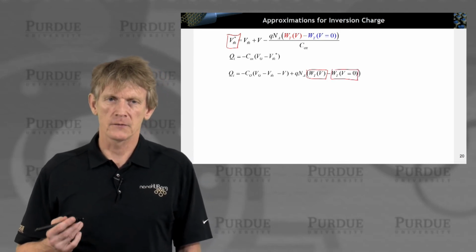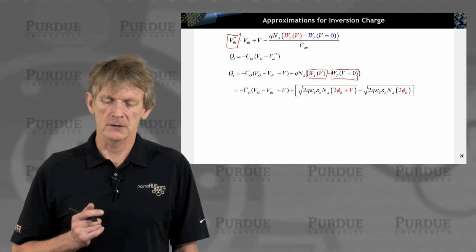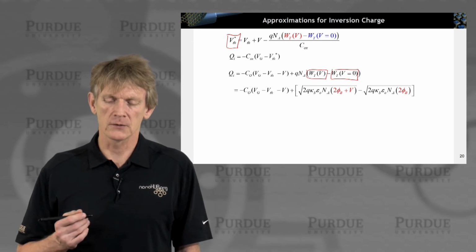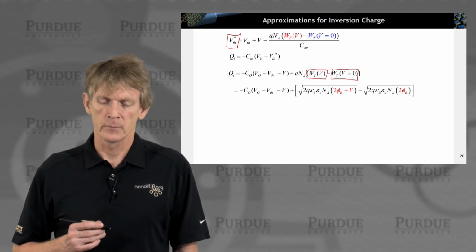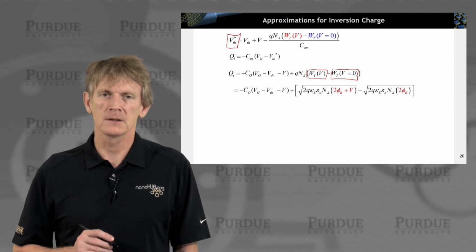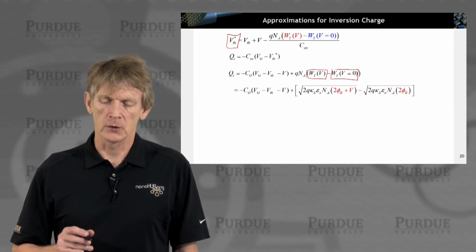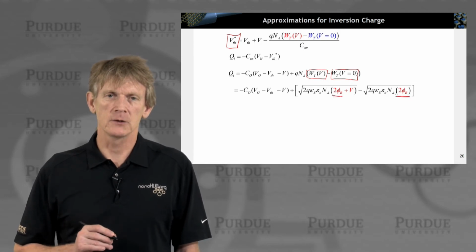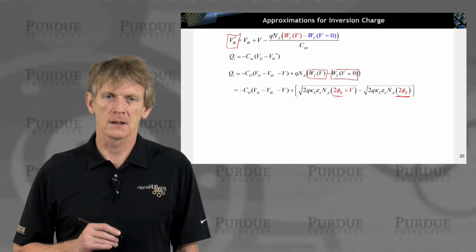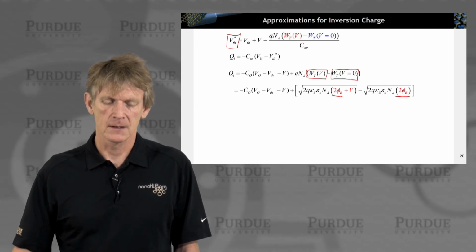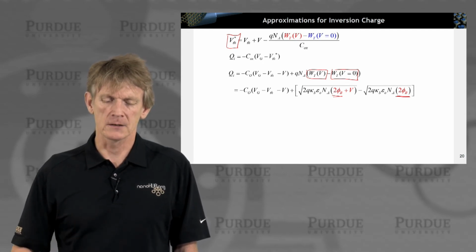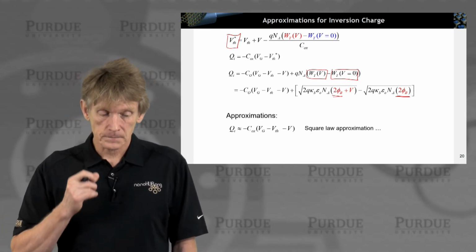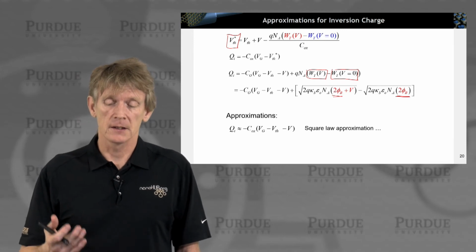And they were functions of applied voltages. We have expressions for those, and here are those expressions. Okay, so we just plug those in. They kind of get longer, but again, you see the square root dependencies on voltages, and we're folding in the 2 phi b, just like what we did in the MOS capacitor expressions, and we have now corrections along the channel like that.